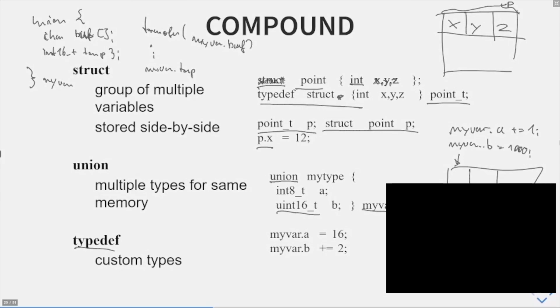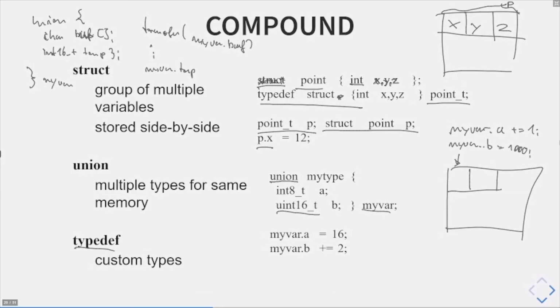So that's what you want to have. And once you interpret it as a temperature, you look at this memory address that is there and interpret those 2 bytes that are there. But the inner mechanism of this is, of course, that the buffer would just be the address to the first byte.